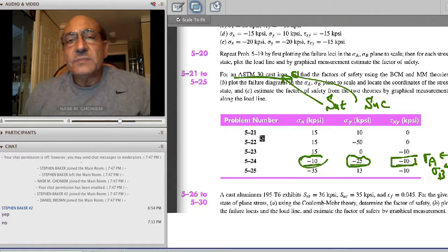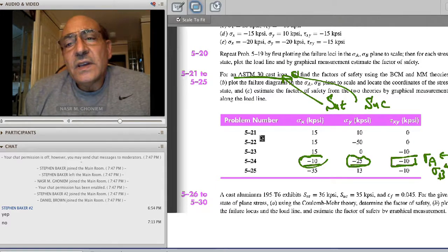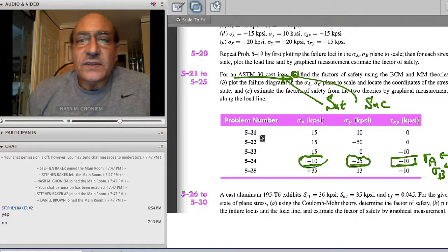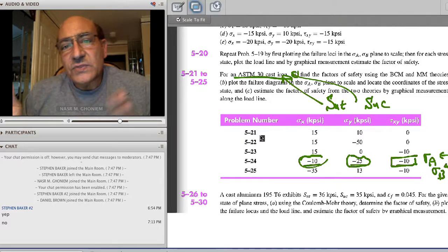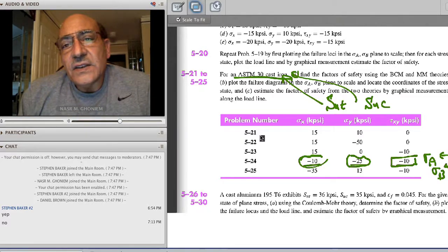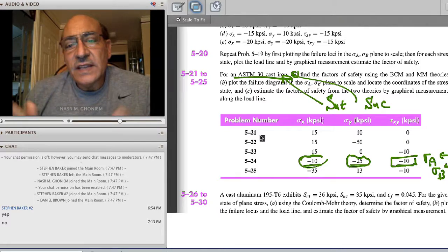And the Brittle Mohr is the box that we've defined. It has, that we talked about before, two straight lines on the sides directly. And the modified Mohr, you extend the box a little bit on quadrant 2 and quadrant 4, and then you connect with straight lines.